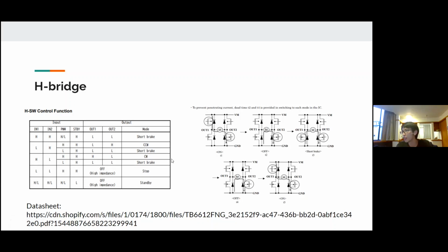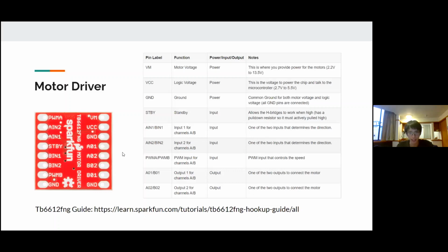But in reality, depending on how you wire it up, it doesn't matter whether it's clockwise or counterclockwise, because you can just try it out, and in case it's not spinning in the way you expect, you just change. You don't even need to change the wiring. You just change the way you define the pins in the code. So say you just switch the 2 pins, and that will reverse the direction.